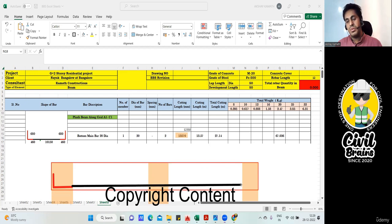Up to here I'll bring my bar, and here I'll lap my bar. So this is my lap length. This lap will happen like this. Give a lap, take it like this, and then this bar will be bent in this way. Got it, no? So this extra lap, whatever you can see, this is your lap length, which is 57 times the diameter of the bar which you have taken. So practically you can do it in this way. Since we are using a 20 diameter bar only, this is one way of lapping. If you cannot lap in the center, again, you have to lap near the support only.